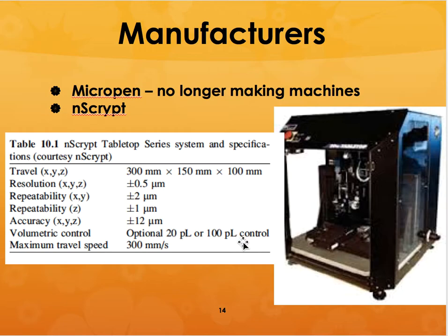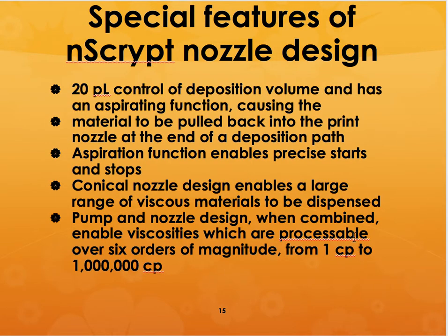For example here, see the repeatability and the resolution. See the higher resolution that you can get with these machines, and compare that with, say, Stratasys or 3D Systems and things like that, where the resolution is of the order of 500 microns. So this is at least 2 orders of magnitude finer resolution, which means it is going to give you better components. That's because of the amount of material that you can deliver. You can deliver extremely small volumes of material deposited at any given time.